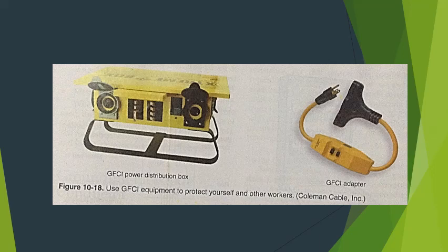All circuits must originate from approved panels or power outlets and must have overcurrent protection. All receptacle circuits and lighting circuits must be separated.